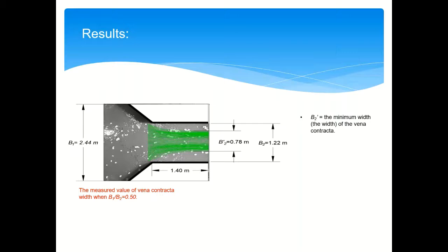Gotcha. Do you know if other people have tried using more or fewer pieces of paper to get better resolution surface velocity measurements? Actually, there is not a certain number for paper pieces because it depends on your velocity. When the velocity is very high, you need to seed the flume very fast with a large number of papers.